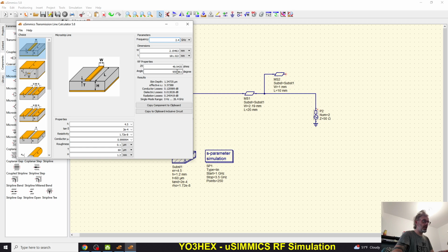What we also know is that we would like to see a phase deviation of 90 degrees, because you have 90 degrees to go and then you get a full reflection because you have an open stub. You have an open stub, you get a full reflection.